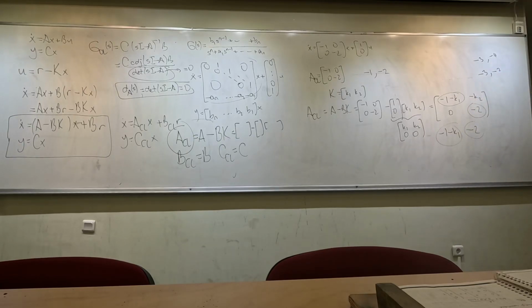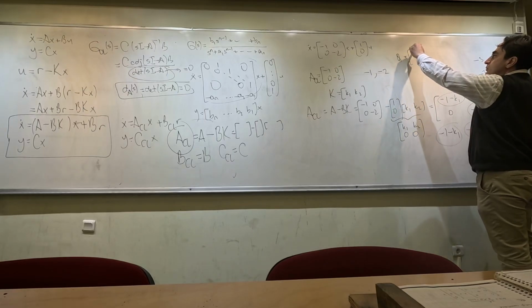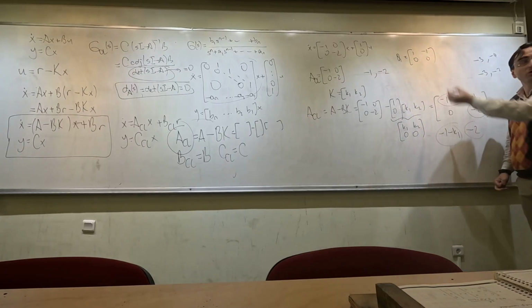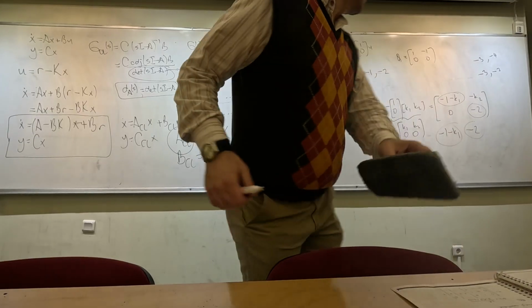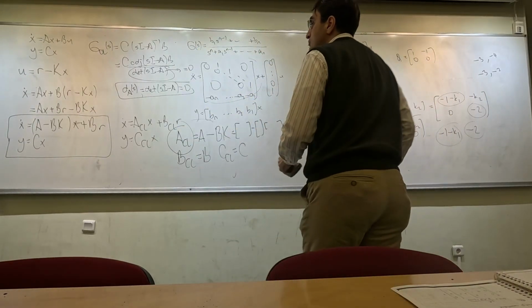So sometimes when your system does not have controllability, you will end up with this type of situation. Okay? This system was not controllable. We have actually solved an example for this. Q for this system is [1, 0; -1, 0]. Determinant is 0. It is not completely controllable. That is why when I try to apply state feedback, I cannot place my closed loop poles arbitrarily in the complex plane. Okay? So this is not going to happen when we have controllability. So that is actually what we are going to write here.